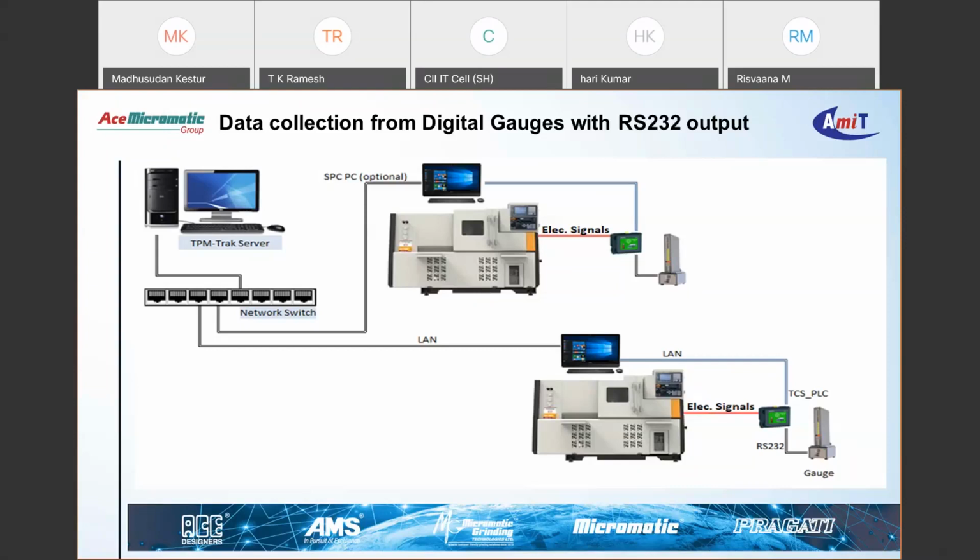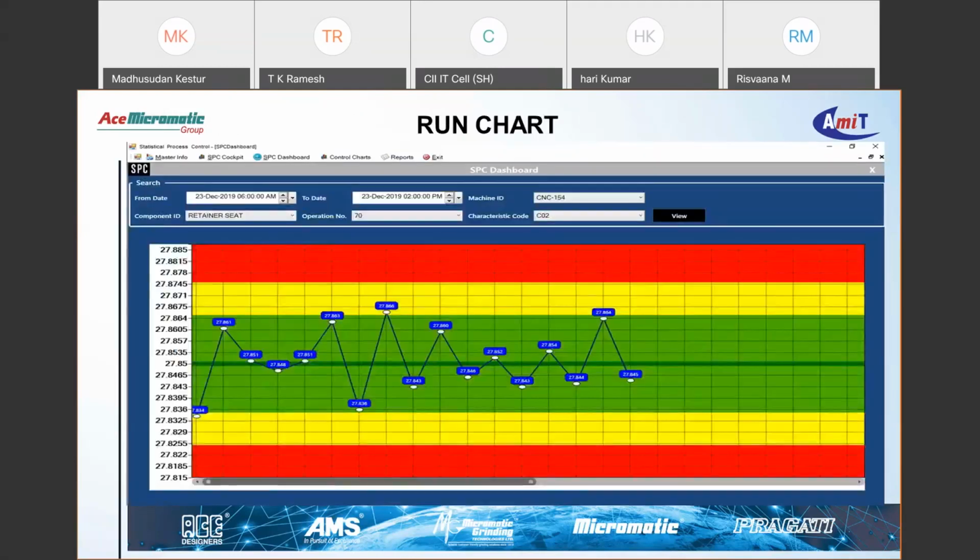To avoid these things, we have automated the process of measuring the tool wear, looking at the control parameters, and intelligently adjusting the offset to make sure that the process is under control. These are called automated tool wear offset correction solutions. This is achieved by deploying certain hardware at the machine and then integrating the hardware to the machine. We also take inputs from the digital gauge into this hardware. The intelligence is built in the hardware to provide the required offset back to the CNC controller.